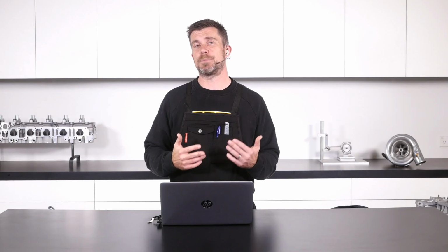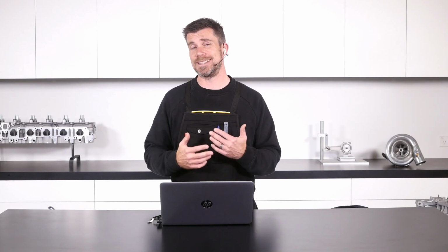Specifically, this is the common trend you'll see on Subaru engines as well as Mitsubishi turbocharged engines, and part of this can be down to OE tuning. However, the other aspect is because that exhaust manifold pressure is climbing so sharply at high RPM, this actually has the effect of overcoming the spring pressure on the wastegate and helping to force the wastegate open.